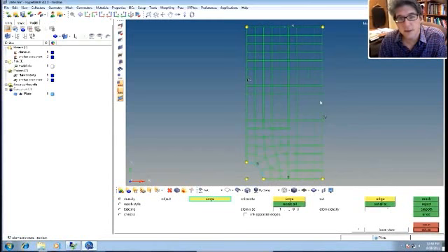And you can see here it gives me a mesh. That's not a bad mesh. If I like it, I can hit return. If I don't like it, I can hit reject. Let's say I wanted to add some more nodes here. You can actually do that. You can use this element density, and I can individually pick an edge. So if I pick the edge, it sets it to 1, because that's what I had the value set to.